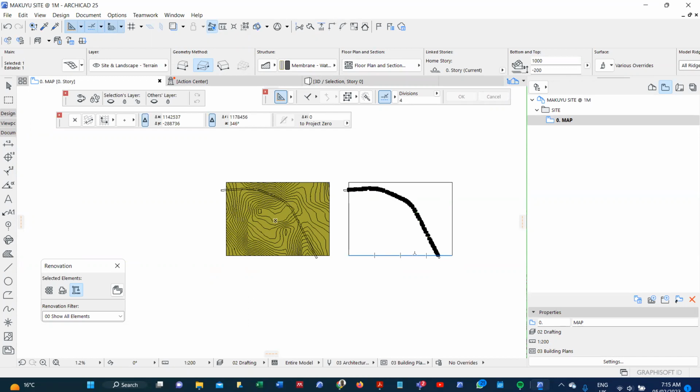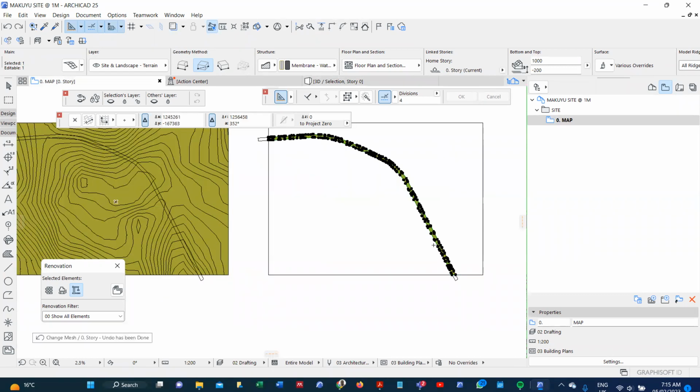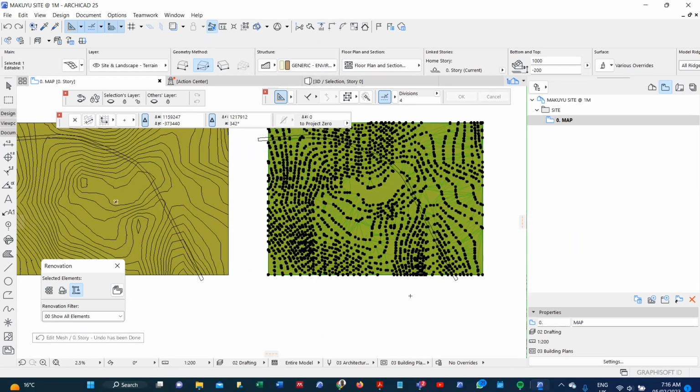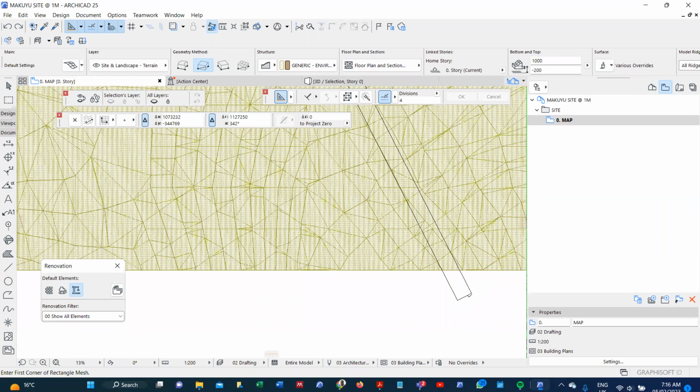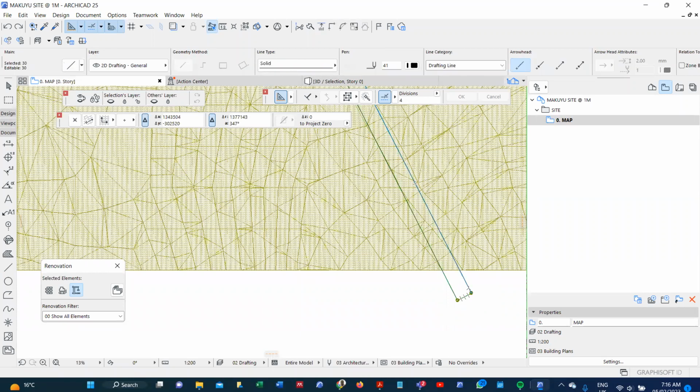But for some of us who know how our roads look, first of all, this one, because of the scale, maybe we need to do that. So allow me to undo what I've just done. This road reserve of 12 meters normally has a road carriage of around 5 meters. Or in this case being 12 meters, it may even allow 10 meters. 10 meters might be big. So let's work with 5 meters.